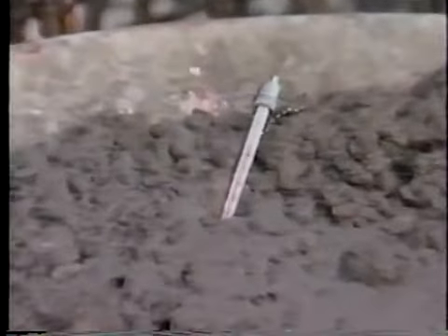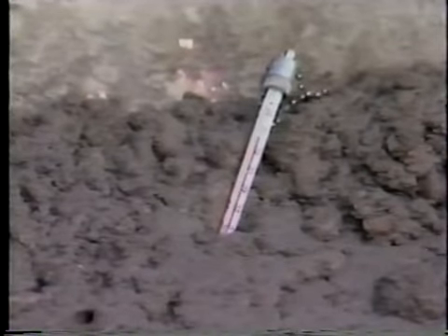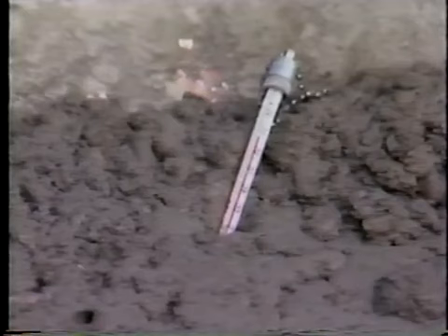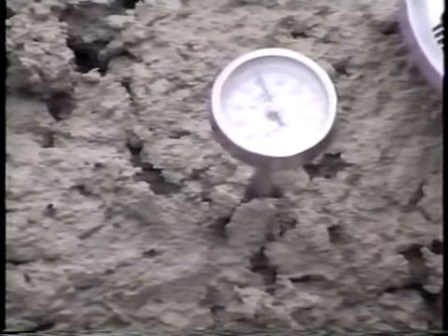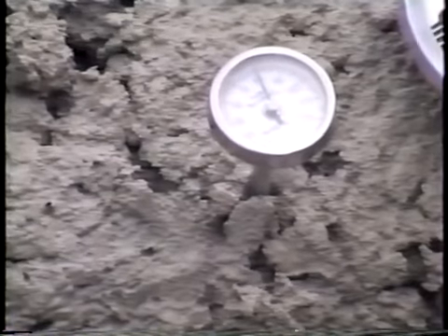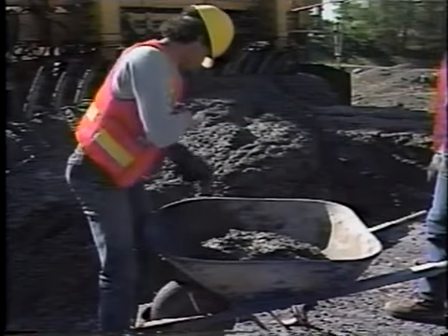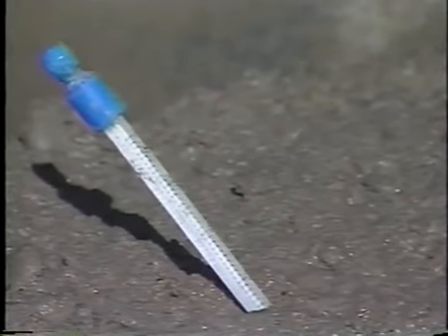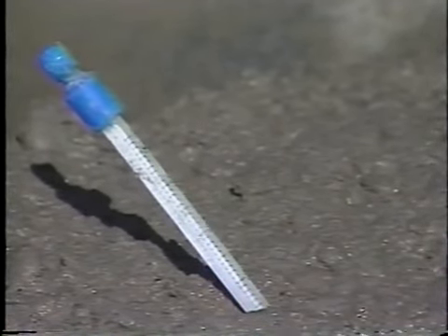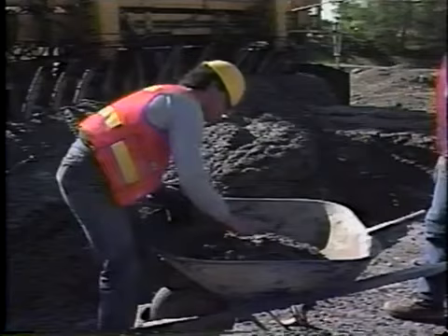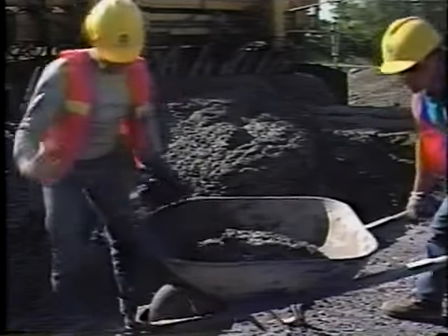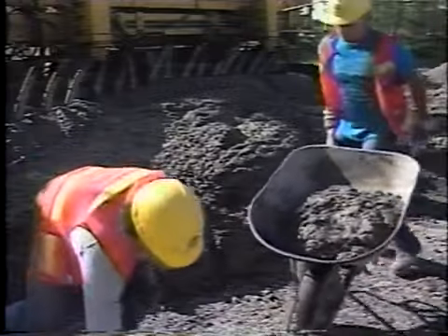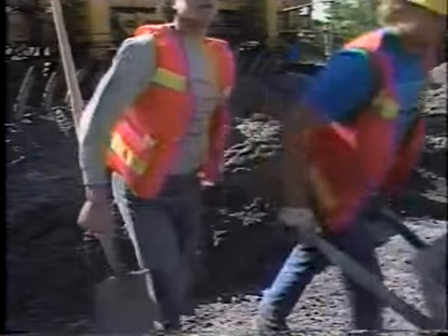All that's needed is a standard thermometer, such as an ASTM liquid in glass type, or a metal immersion type. The thermometer is inserted into the fresh sample so that the temperature sensing portion is submerged at least 3 inches. The concrete should be gently pressed around the thermometer so that the air temperature does not affect the reading.